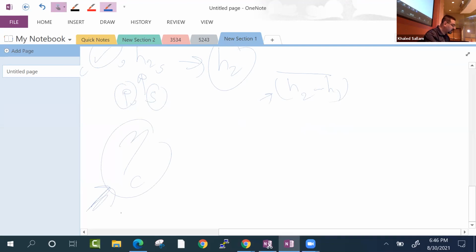So in that case, again, the efficiency will be given, or you will find it from the literature, and you will use it to calculate the actual H2 instead of the H2S. That's not practical, this is the real one. And you will see the difference in the compressor work, and you will see how much it really changes the COP, right? So in task 5, we work as our own devil's advocate.